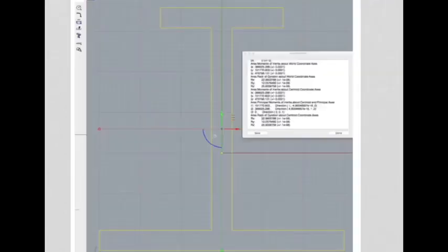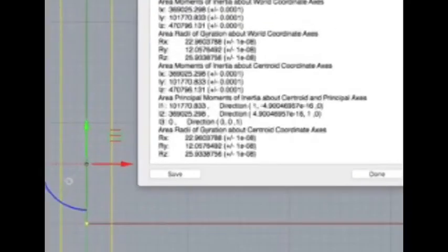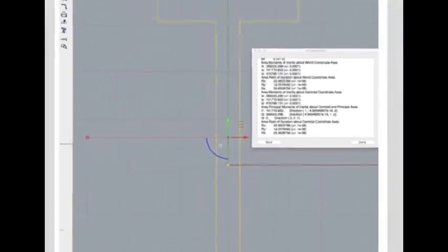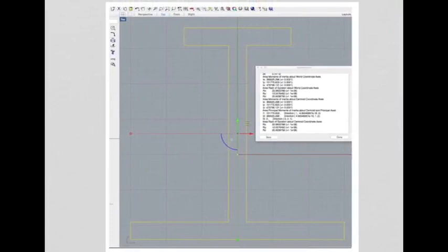Now, some good news, there are other ways of finding K and I other than by working it out. You can use a CAD system, and provided you get the axis in the correct position, you can request the CAD system to give you K values and I values. A little bit indistinct here, but there they are. That's software called Rhino being used to find I and K, but virtually any modern CAD software can work these values out for you.